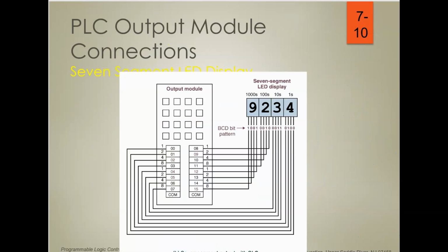And then on the output side, what we have is 7-segment LEDs, and you know how the 7-segment LED works. That's basically in the opposite direction. So the binary value of every single digit will appear at 4 terminals.